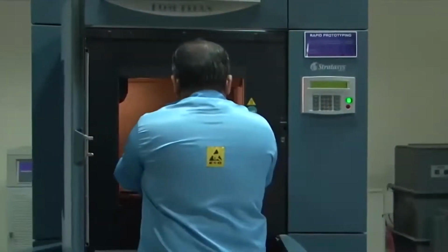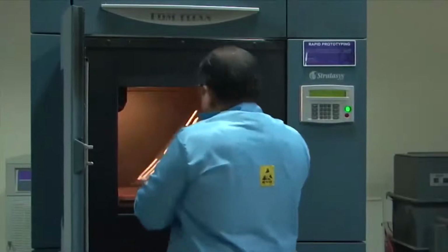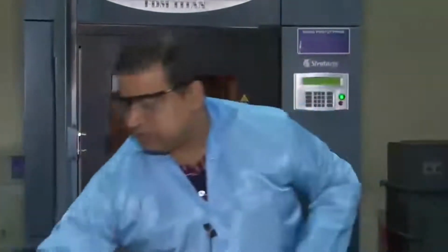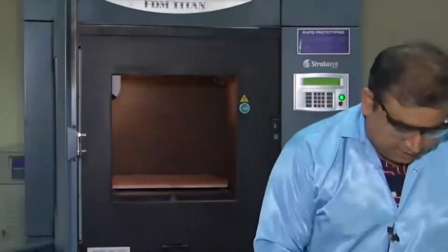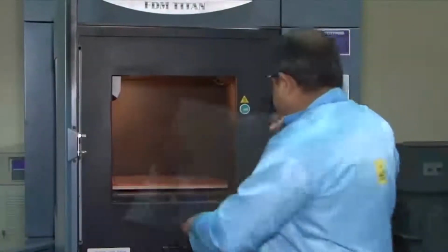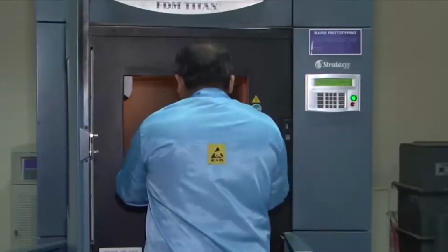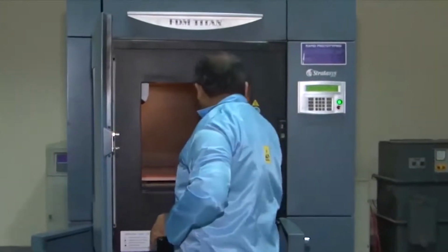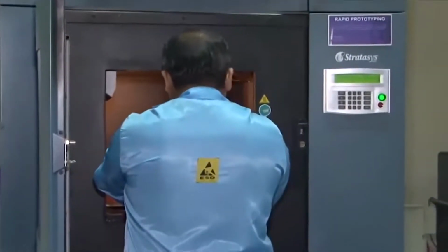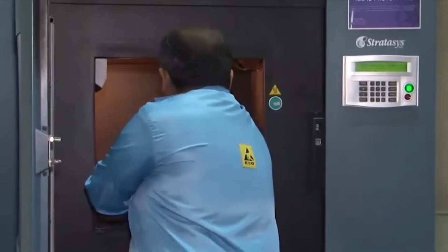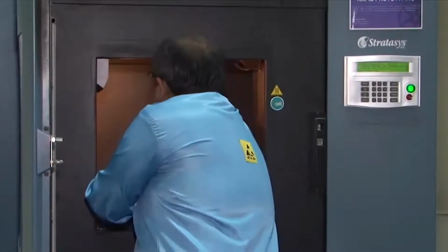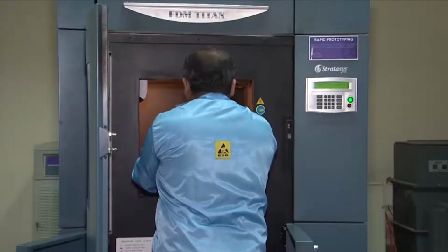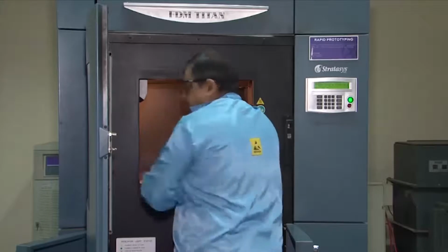We cannot leave the temperature on for a long time because this is the Mylar sheet from the last run. I am going to remove this Mylar sheet and put our sheet here so that this becomes a new run of the process. The oven is getting heated up to about 119 degrees Celsius, so it is a little risky to touch the sample surface at this stage, but you have to ensure that the sheet you are placing is at the very corner, and there is a guide there which ensures that it is at the corner.